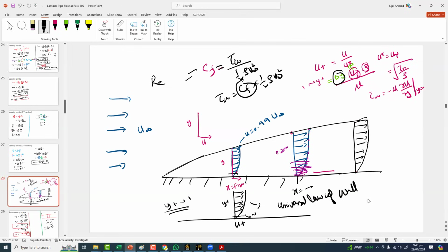But see one thing about internal flows. If we talk about pipe flow, it's an internal flow, and it has to be resolved with enough mesh. If you resolve this flow properly, then y plus will also be taken care of very carefully. For internal flow, all the flow will mostly be in the boundary layer, because the whole pipe flow is in the boundary layer. But for external flow, only some region is in the boundary layer.